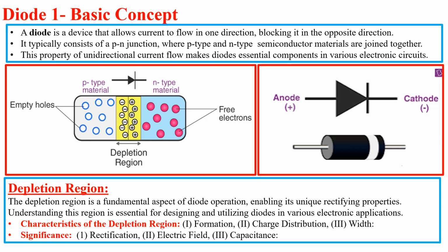In other words, the depletion region is widened. This prevents charge carriers from crossing the junction and effectively blocks the current flow. Only a very small current, which we refer to as leakage current, may occur until the breakdown voltage is reached.